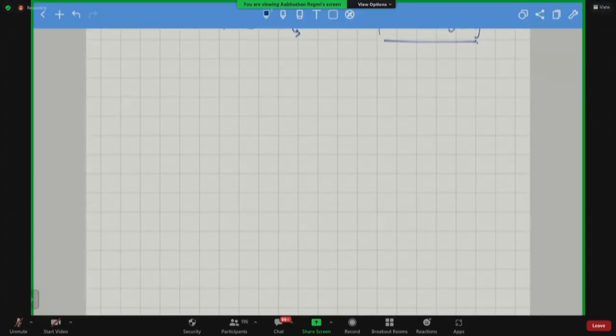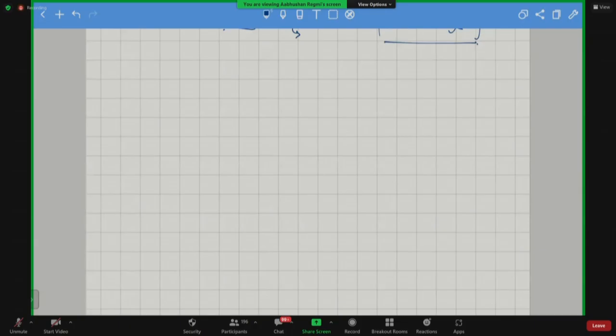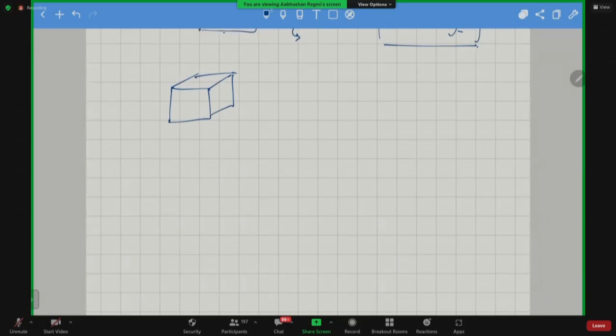Okay. So I'll just describe what geometry we're trying to do over here. I don't know if you guys have seen this sort of geometry before, but as we already know, there are so many different things that you can do with blockMesh. Essentially, the concept behind blockMesh is that you have these hexahedral blocks. That is what OpenFOAM calls it. These hexahedral blocks are nothing but 8 vertex geometries.